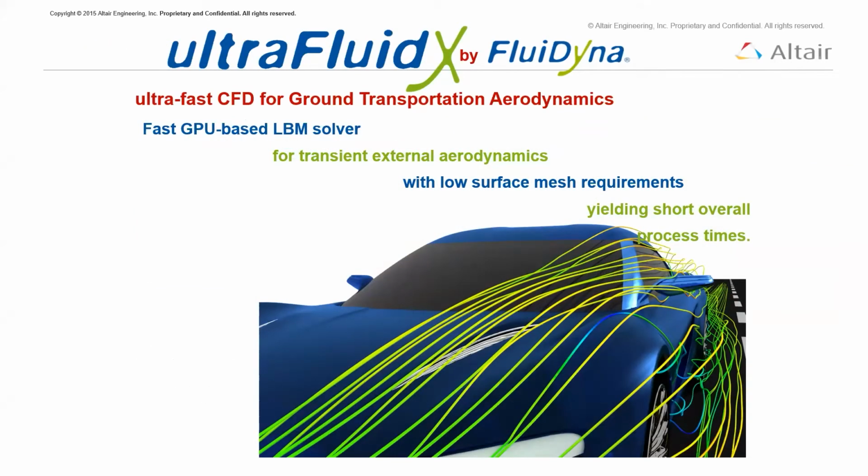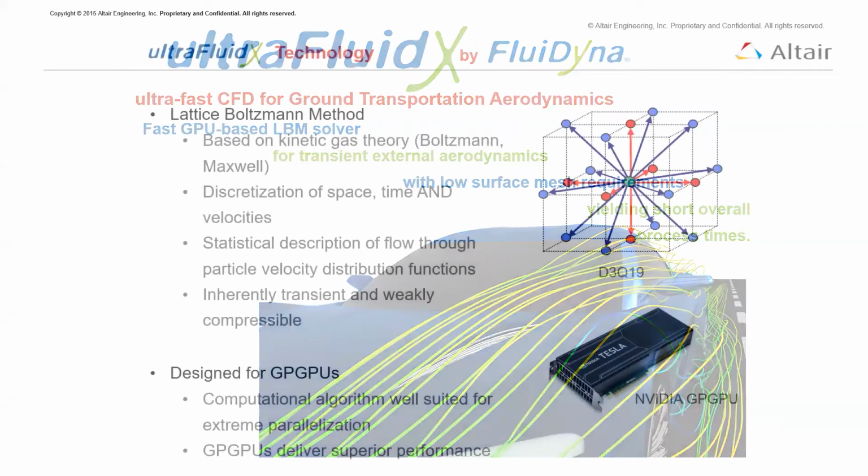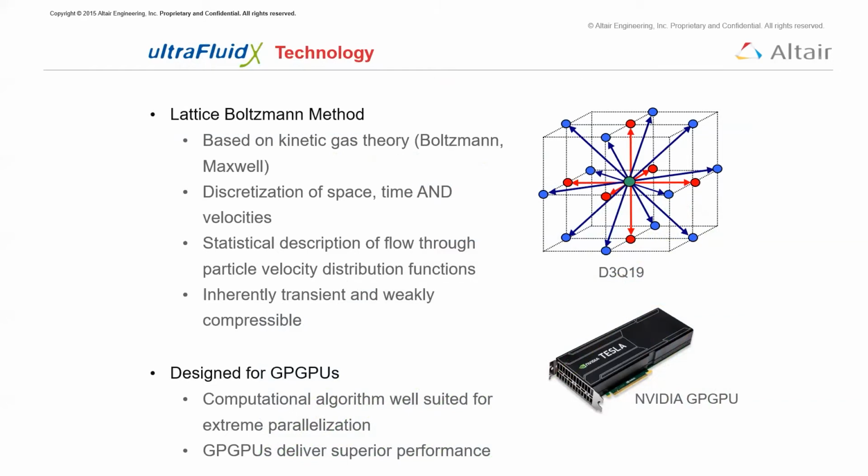Now, UltraFluidX, the reason the majority of you likely won't be using this one is because UltraFluidX does require access to GPU hardware. Typically, we find most students have access to CPUs only, which requires you to run AccuSolve. UltraFluidX, if I jump to the next slide here, does run on the lattice-Boltzmann method. It does require GPUs.